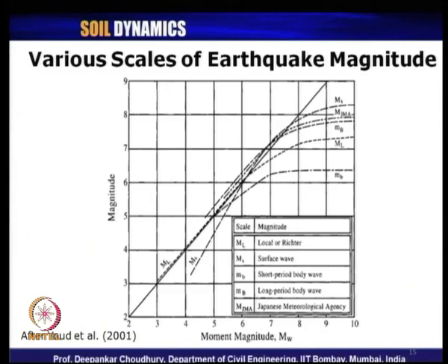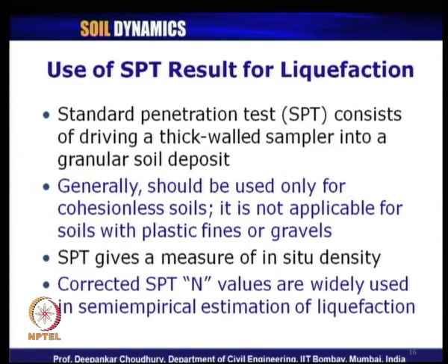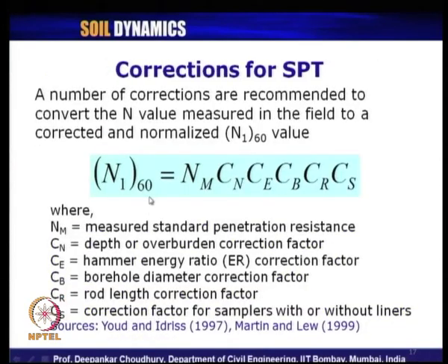So, if the given input data is for any other earthquake scale, we should use this conversion chart or conversion table to find it out in terms of moment magnitude of earthquake. Now, to use the SPT, that is standard penetration test result for liquefaction calculation, we have seen what the steps are. We have to use the corrected N value, and the corrected N value is computed by using this expression